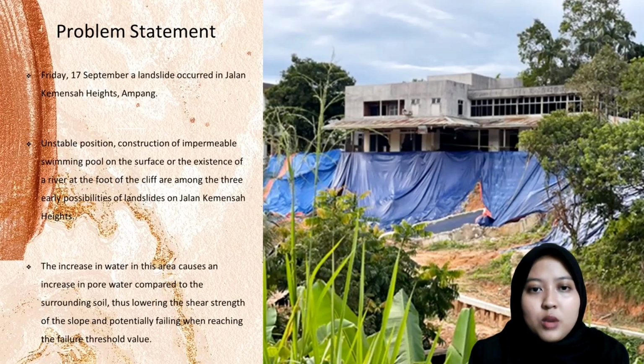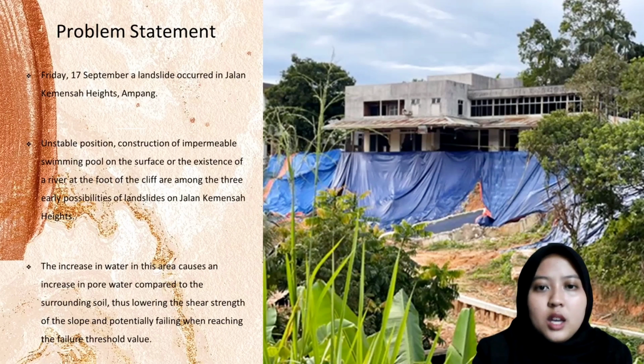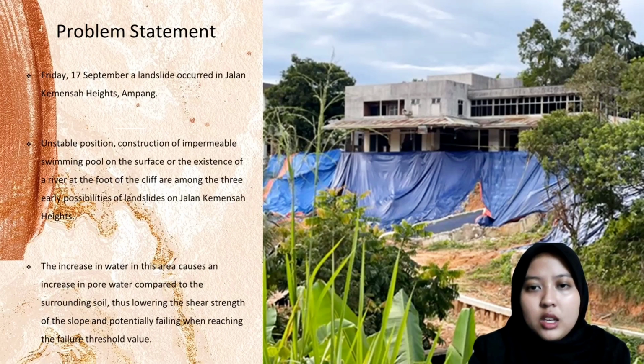The increase in water in this area causes an increase in pore water compared to the surrounding soil, thus lowering the shear strength of the slope and potentially failing when reaching the failure threshold value.